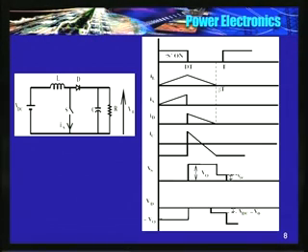So anode potential is VDC with respect to the ground, cathode potential is V0 with respect to ground. So what is the voltage across the diode? It is nothing but VDC minus V0, and V0 is higher than VDC, so it is a negative voltage.